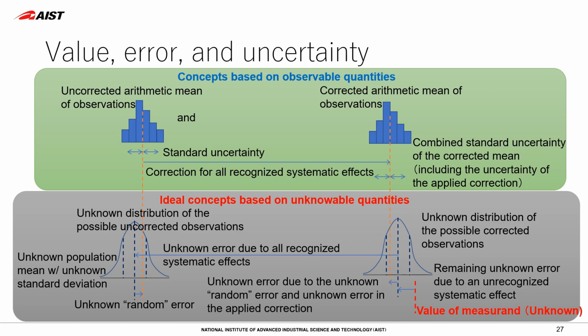However, this is not identical to the value of the measurand. There still remains unknown systematic error that causes a deviation from the measurand. The remaining unknown error may include incompleteness of the definition of the measurand. Just the value of the measurand, what we really want, remains unknown. Now you understand what the note associated with the definition of uncertainty means.